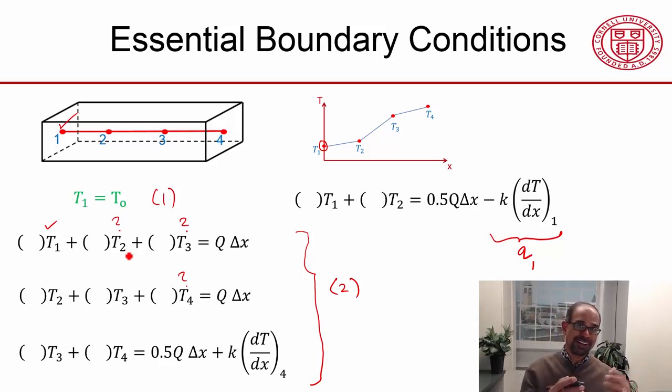So you're inverting a 100 million by 100 million stiffness matrix for very complicated problems. And if you do it cleverly and you have very fast computers, you can do that with today's computers. And then after stage 2, I know all my nodal temperatures. So all the nodal temperatures have been determined, and I basically know my temperature distribution.